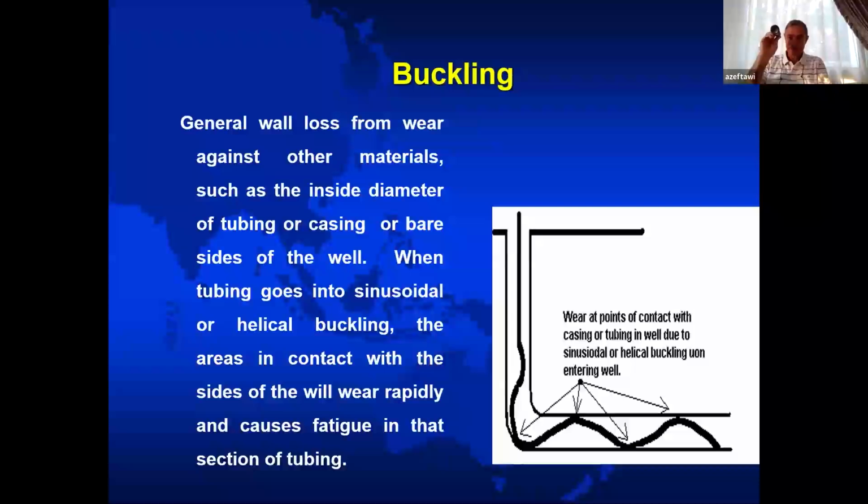This pipe, you have to have two things here. To be able to push this pipe farther, deeper in the horizontal section, you need to have wall thickness and bigger diameter. These two factors, the thickness and the diameter, give you the rigidity which is required to push the pipe without causing the buckling.